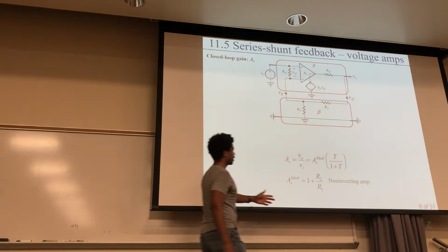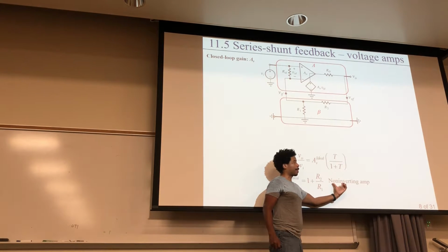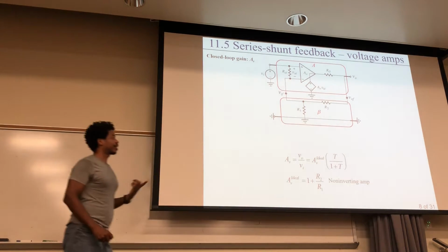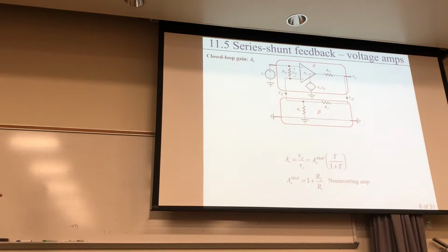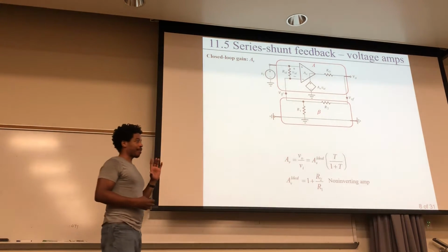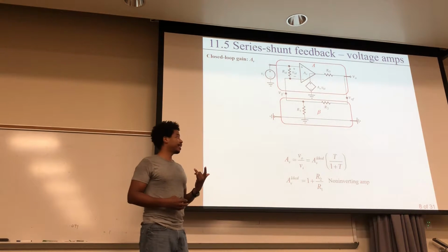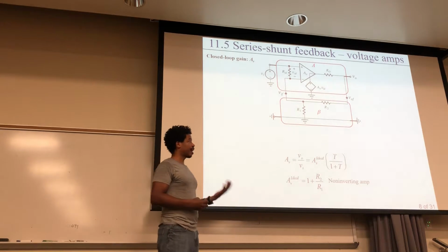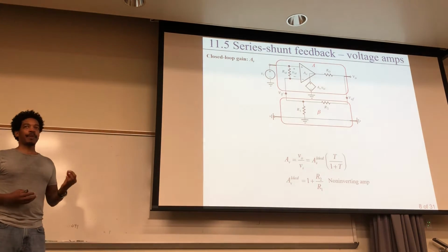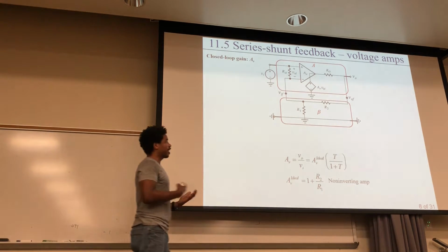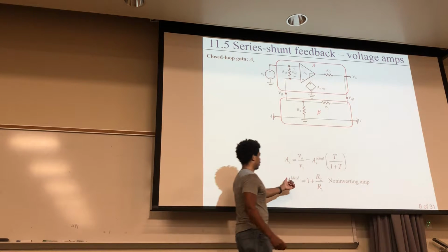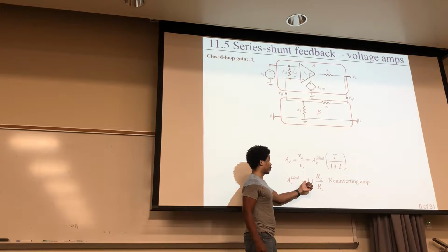Okay. But let me ask you this. Do we all understand why op amps are called inverting, non-inverting? Okay, so if your op amp inverts its input, like it's just some magnification factor, but it's negative, if there's a sign change, then not only did it get amplified, the phase is 180 degrees out of phase. So that's one way to determine if it is an inverting op amp. If there's no phase change like that, then it's called a non-inverting op amp. In this case, this is not going to be negative. If it's inverting, this would be negative, of course, but this is not negative.